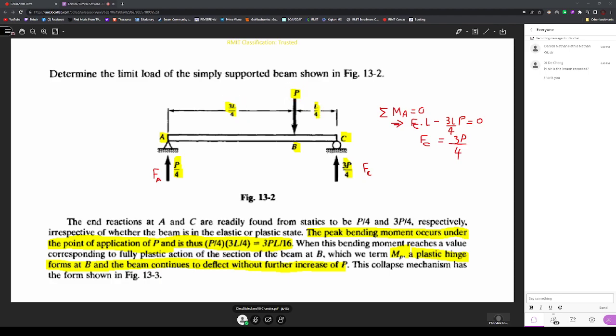Okay, so the first thing is when the load increases to plastic load, what happens? There are plastic moments created at points. So the first point we can expect to get a plastic moment is where the load is acting. Okay, so the other 2 points can be where the load is supported, so where there are reactionary forces acting on the mechanism. All right.